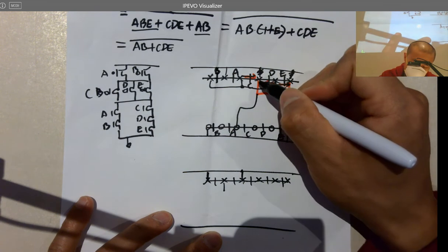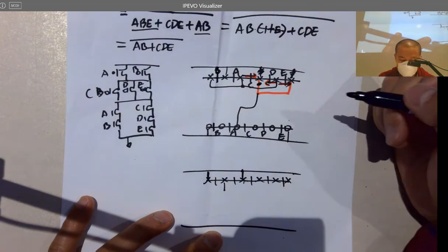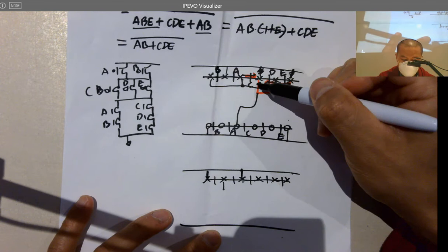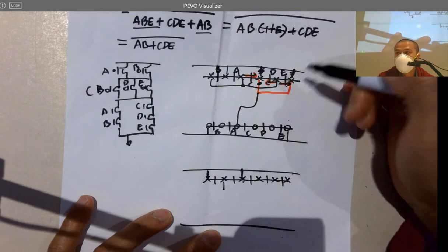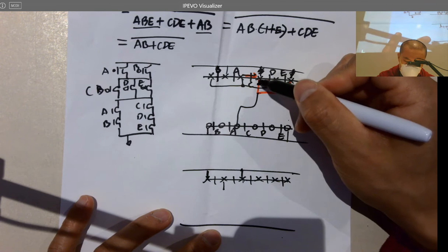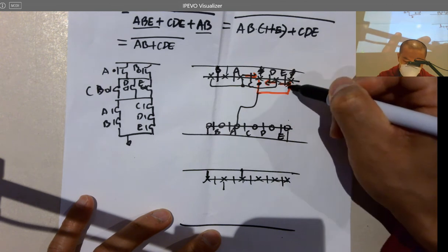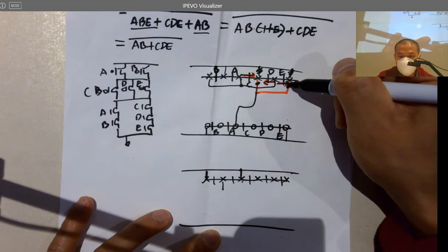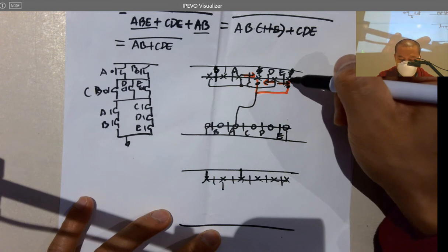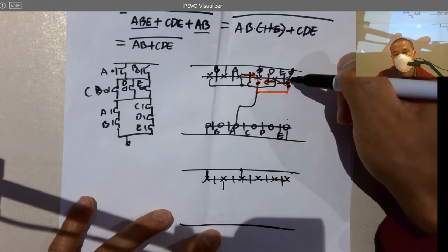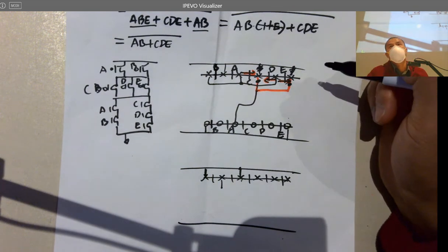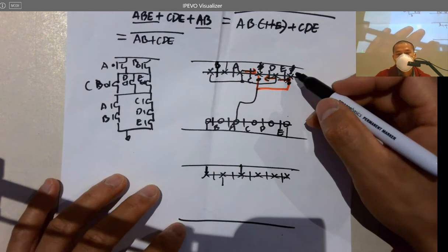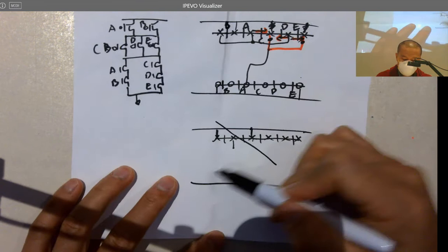So the way to do that is you introduce a via here to drill a hole to the top layer, to a higher layer, to get a metal 2, and then make the connection. So metal 1, still metal 1 here, and then metal 2, and then drill a via to get the trace 1 layer down to short it to metal 1, and then short to this diffusion, or the N+. So I'm going to cover the semiconductor basics this week, and probably 1 or 2 lectures next week as well, to understand what are these materials. Okay, so this won't work.